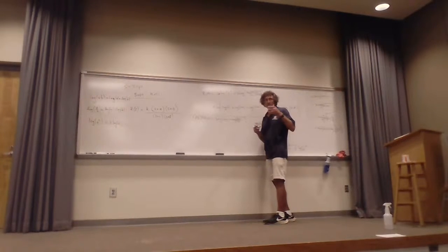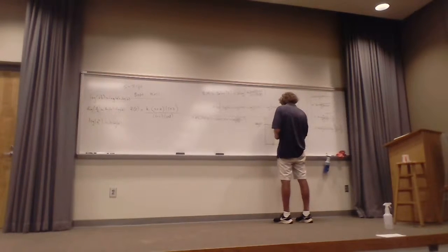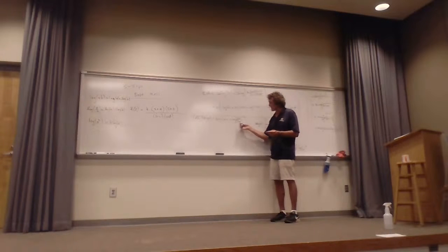You've heard the term 3 dB point over and over. That's the point where all of a sudden a single pole or a single zero becomes the dominating factor. Beyond that point, y'all follow me? So really, in truth, we approximate these. If this is A here, we just draw a straight line to that, then we start going down. And notice this right here. For omega greater than A, a lot greater than A, then this is really just 20 times the log of the square root of omega squared over A squared, or really just omega over A.